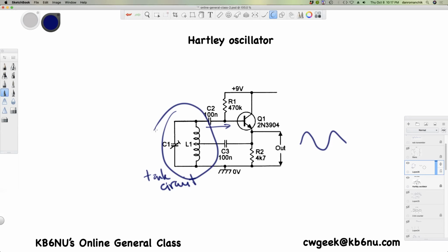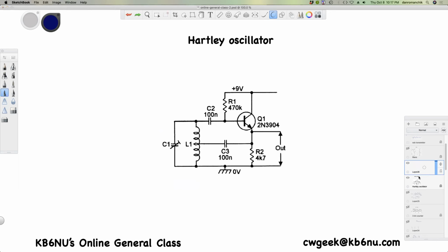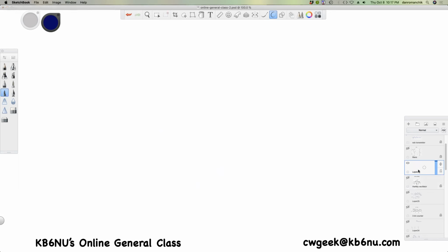All right. So let's talk about amplifiers. There are different classes of amplifiers, A, B, C, D. And really what these amount to is the portion of the cycle, let's say if you had a sine wave input, over which the active component in an amplifier would be active.